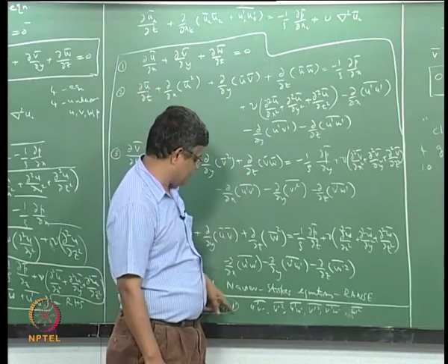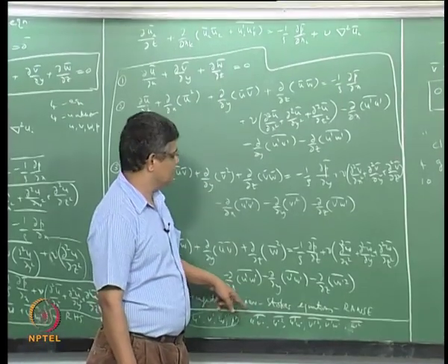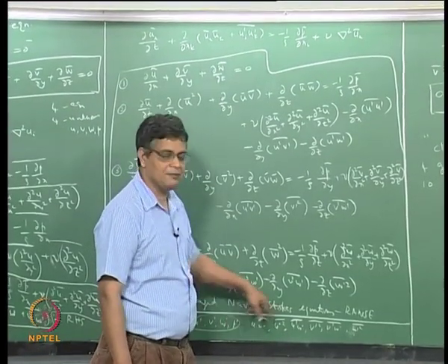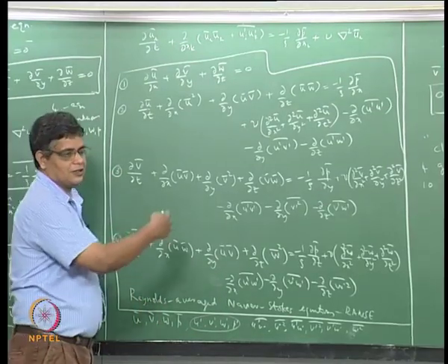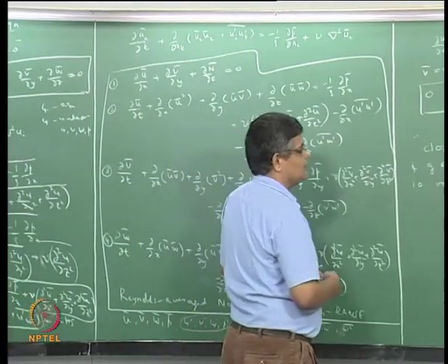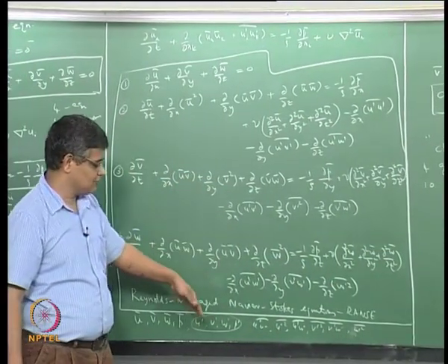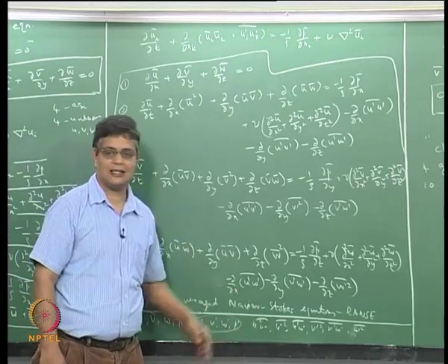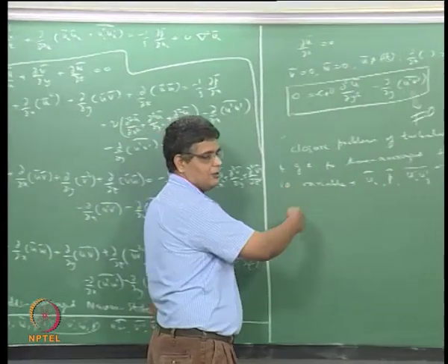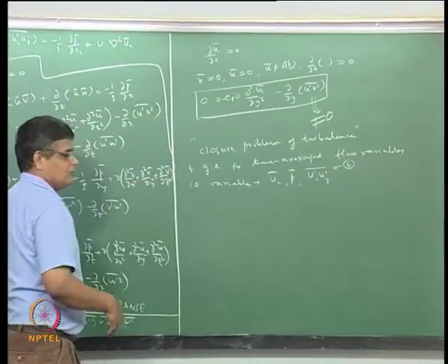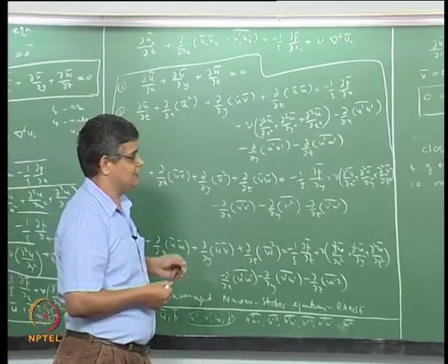If we write an equation for u prime v prime bar, then we may get u prime v prime w prime, which again becomes unknown. So the problem of closure cannot be overcome by further averaging and manipulations of the basic equations.